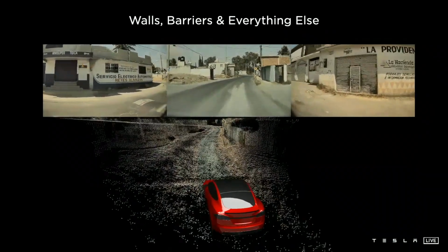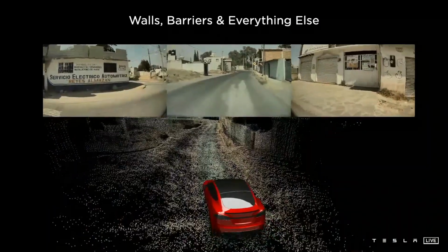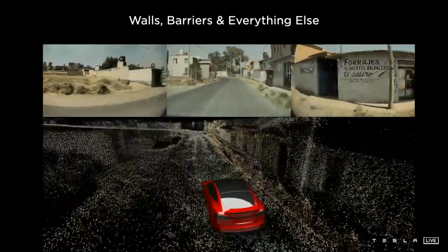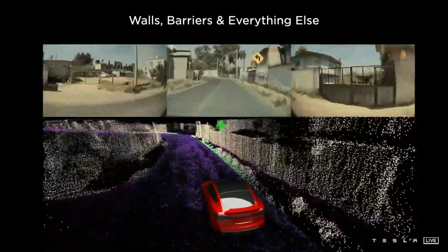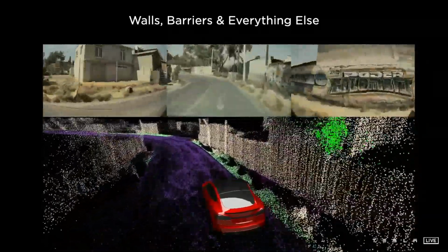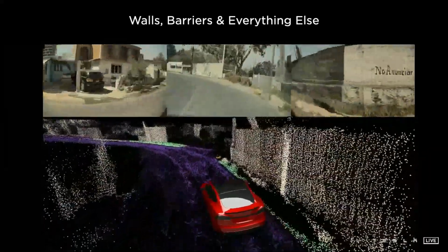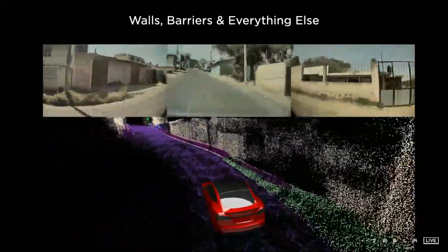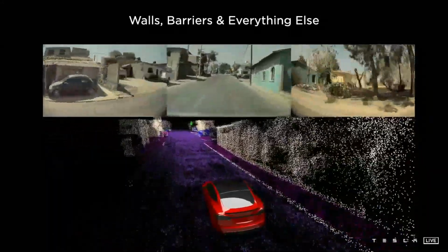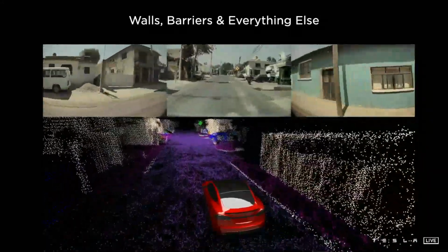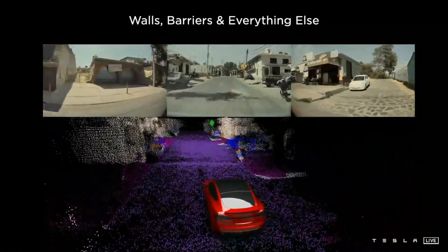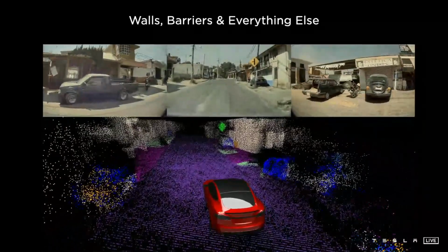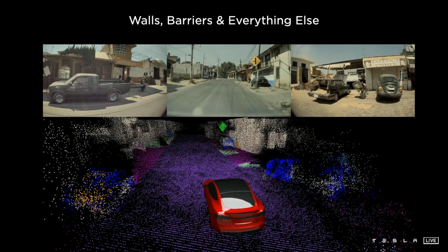We don't have to stop at just the road surface. We can also arbitrarily reconstruct 3D static obstacles. Here, this is a reconstructed 3D point cloud from our cameras. The main innovation here is the density of the point cloud. Typically, these points require texture to form associations from one frame to the next. But here, we are able to produce these points even on textureless surfaces like the road surface or walls. And this is really useful to annotate arbitrary obstacles that we can see in the world.